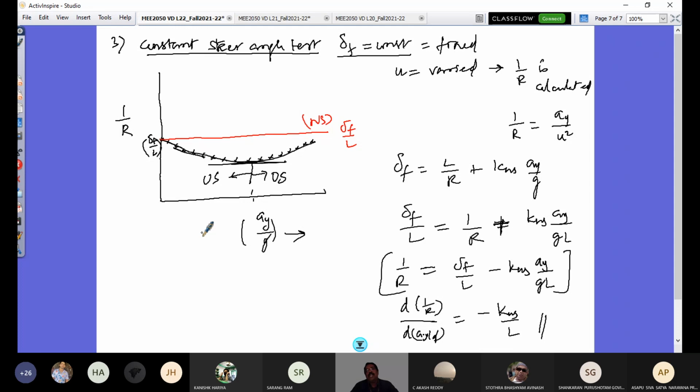Every time you change your tires and do your test, you see the variation in the handling behavior, how it is pronounced in your vehicle. That helps you to make a quantitative assessment of handling behavior of various vehicles on the test track. So these are very popular test tracks to account for real-time behavior. Of course, we looked at the steady state equation with the limitation of a linear tire model and no suspension considered. Quite a sufficient model to develop some physical insight further.